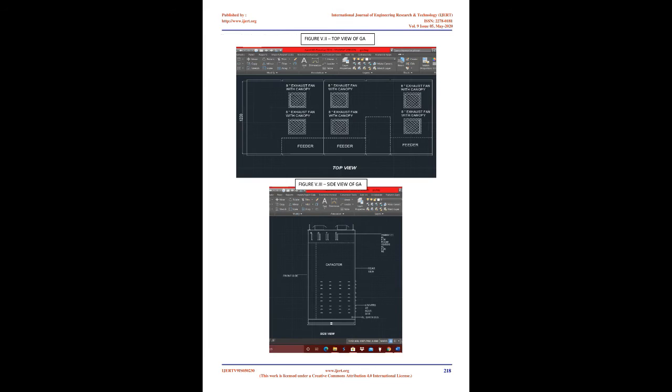3. Penalty reduction methods. Existing methods. 1. Static capacitors. In the passage of time many methods have been used for power factor correction. One mainly prevalent method is that of a static capacitor bank. In this method, capacitors, normally known as static capacitors, induce a leading current and partly or completely neutralize the lagging reactive component of load current. This raises the power factor of the load.